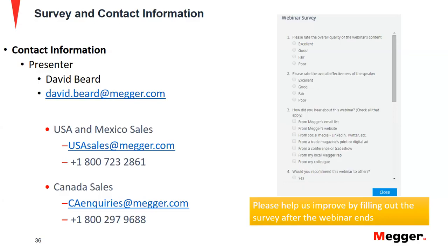David, I think this will probably be our last question we have time for. How do you perform a wiring check test? What we're referring to in here, a wiring check, I'm assuming, is trying to perform a check from the test set, verifying that the correct currents and voltages are actually wired to the relay properly. Whether they're connected to the back of the relay where we're connected to it on the bench, or we're also doing test switch